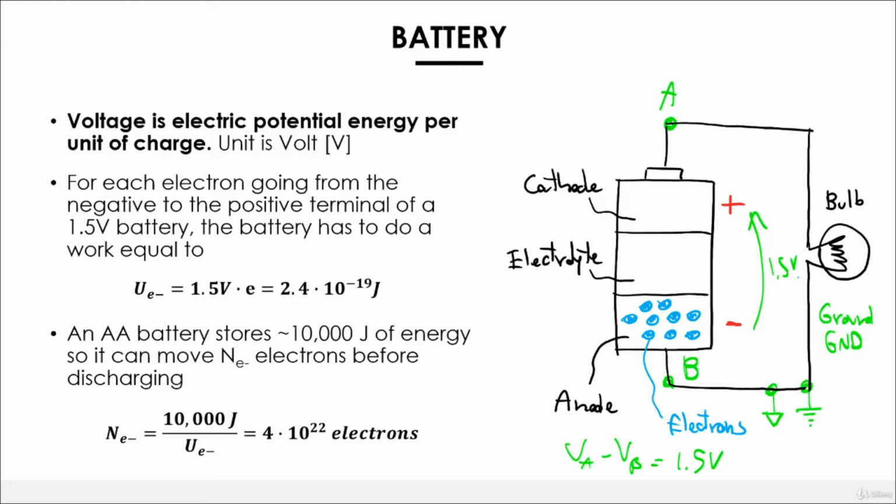These symbols imply that that node is physically connected to the earth, to the ground, under your house, for example. The reality is that it's not true most of the time. Think about a mobile phone. It's definitely not connected to anything. It is a standalone device. But the symbol is used nonetheless to indicate that that node is the node considered to be at 0 volt.